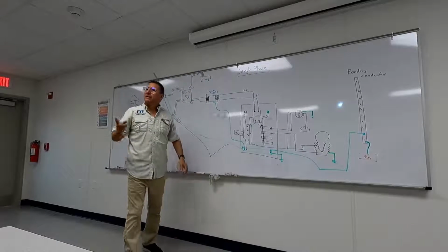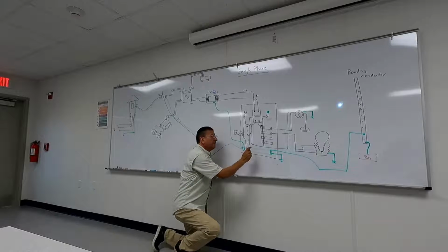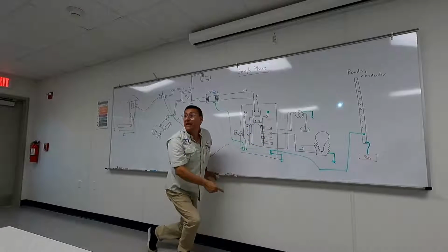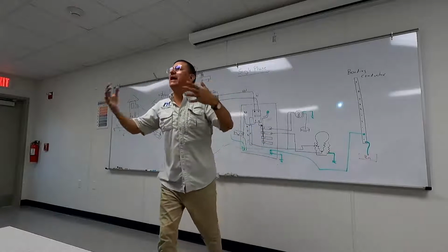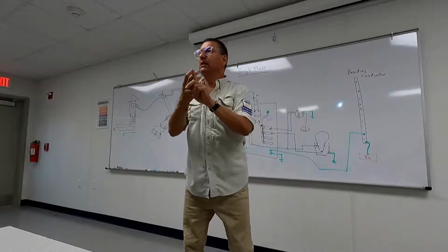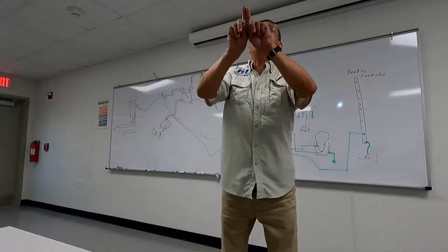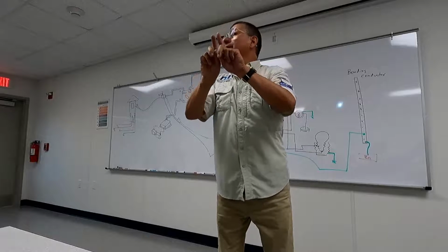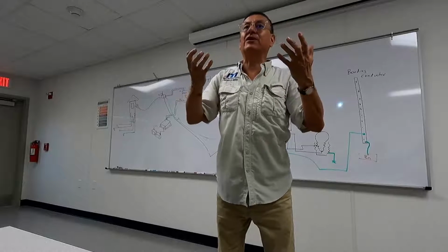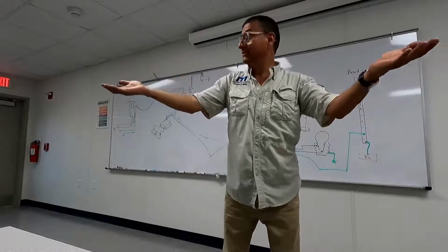Okay, pay attention. Look at this. Guys, in this moment the ground bus bar is connected with the bonding. You remember what the enemy is when you have two dissimilar metals in contact with water? Galvanic corrosion is accelerated. If additionally between both metals I have a leak of current, the arc of current between both metals accelerates the corrosion, and the more noble attacks and erodes the less noble. That's clear, no?